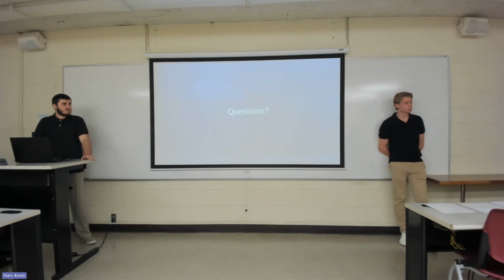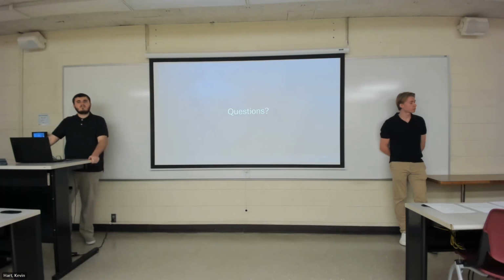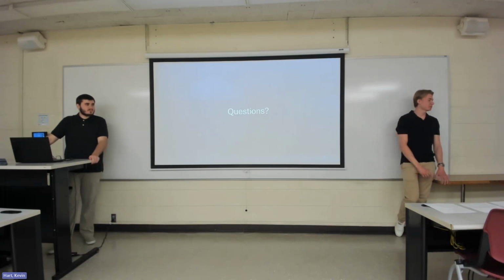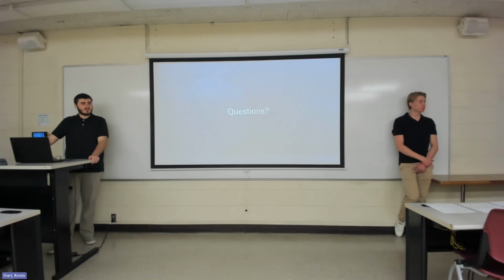A related thing: those are two load cases you picked, that's okay. But then you also need to comment on static failure and dynamic failure. Both need to be considered. You may not have done the fatigue calculations yet, but you want to have some approximation of what you expect out of the new design versus the old design. A static calculation is good, but your system is a dynamic system. It has to last an X number of cycles. Yeah, that's a good point.